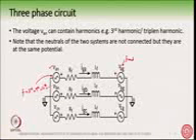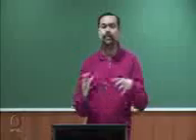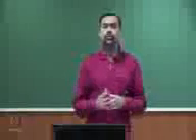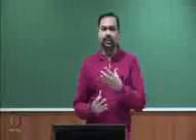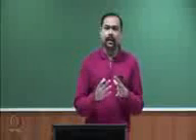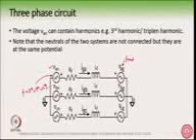Suppose you add only the third harmonic, then it is something we have studied earlier, that you can add triplet harmonics to maximize the DC bus. If you use space vector PWM, you are basically adding all triplet harmonics, 3rd, 9th, 15th, etc. But where are you adding? You are adding into the VAN voltage. So this voltage VAN is maybe a single fundamental voltage source. If you use sine PWM, it is just a fundamental voltage source.